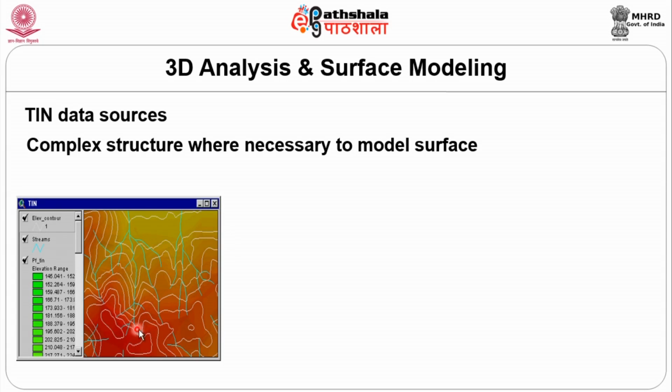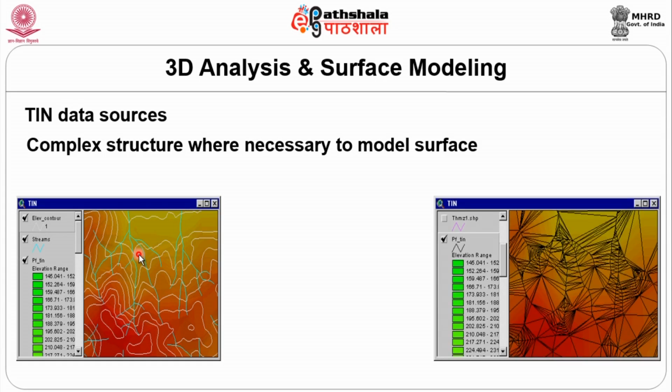One of them you can see here, in which you find the entire area. You also have the contours and the drainages which are running across. So you have two different aspects, namely the contour and your drainage system. If you want to visualize the flow of water, for example, then this sort of a model will be very important, because here you know the z value through the contour part of it. Create that TIN, because you can just convert these lines into point data, or you can use the lines themselves as input. Create the TIN, and then, as I was telling you, superimpose your drainage map over that and analyze. In that sort of a case you require that.